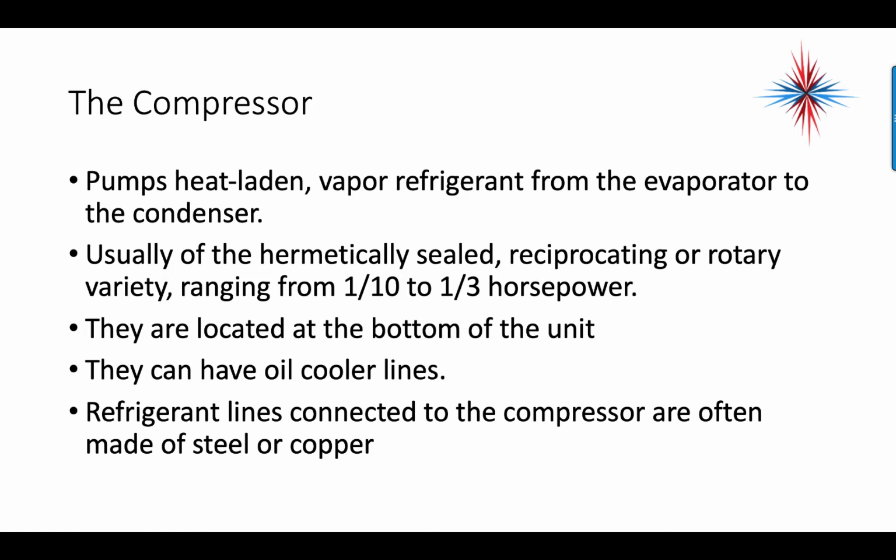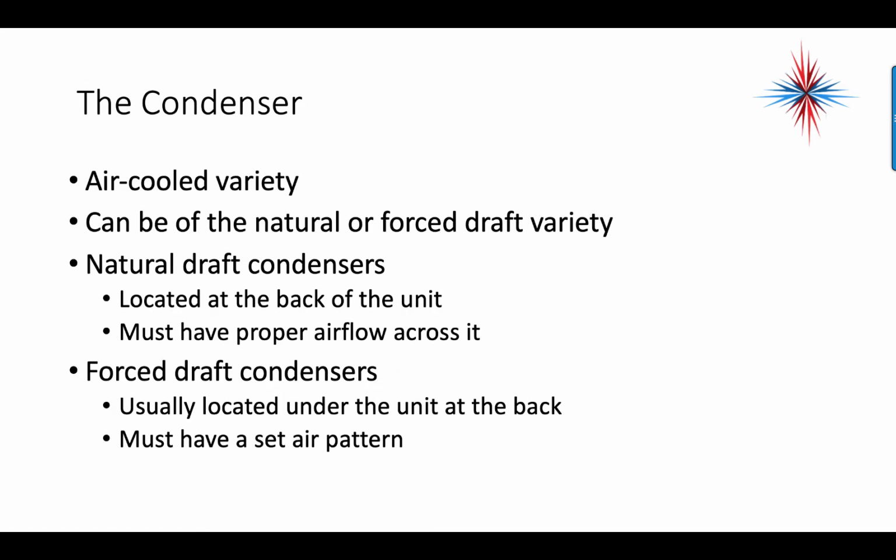They have oil cooler lines, and the refrigerant lines connected to the compressor are often made of steel or copper. Be careful if you ever have to weld in or braze in a new compressor. You might have to use brazing paste because there's sometimes steel lines.